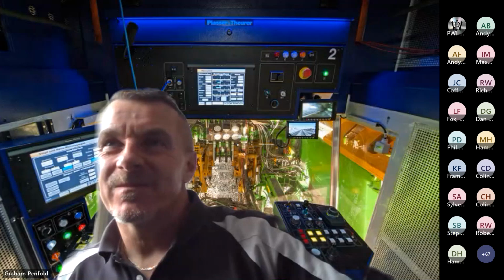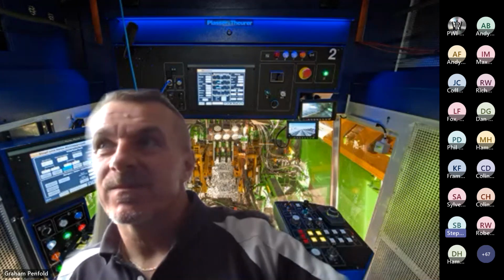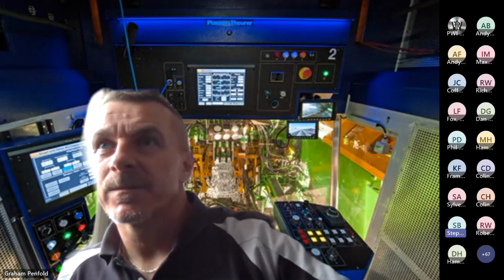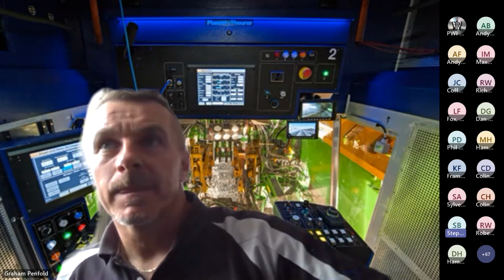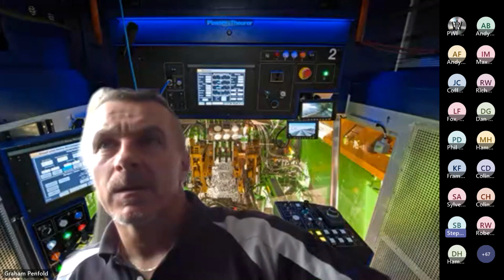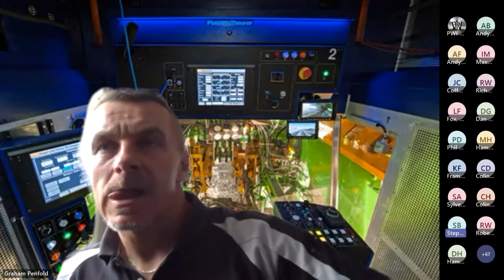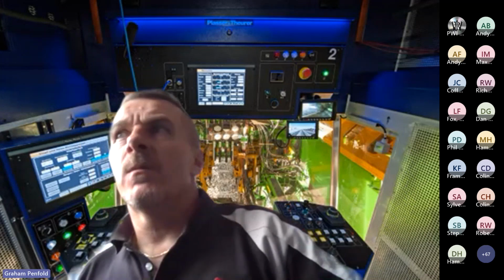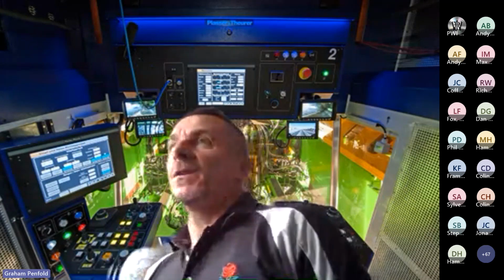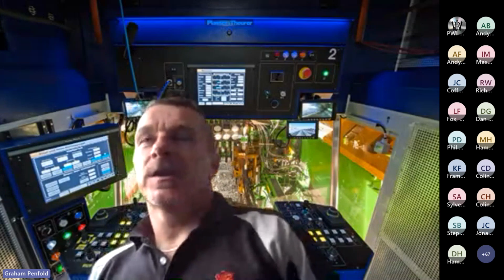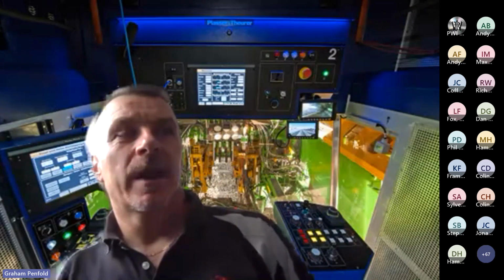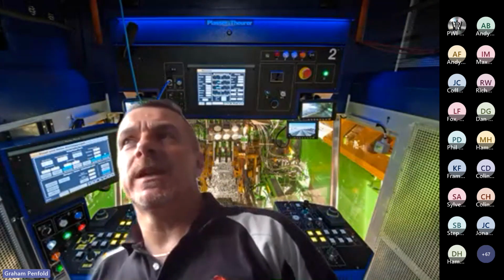John Paul uses overlift with larger lifts, but in the range 40 to 60 millimeters. So getting on to the maximum sensible lift you would ever apply with a tamper. Would you use design overlift with lifts in that sort of range? It depends. It depends on various things. On the clearances, certainly not on the wires. To me, you don't need to.